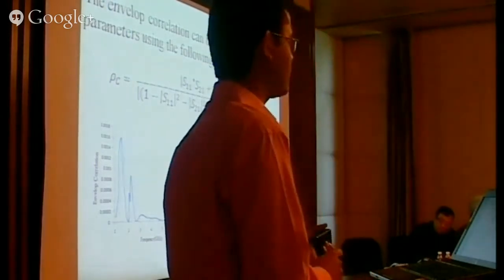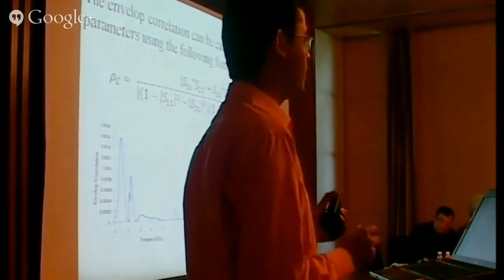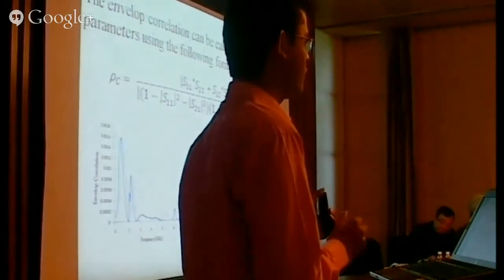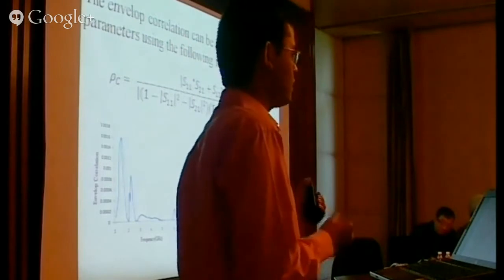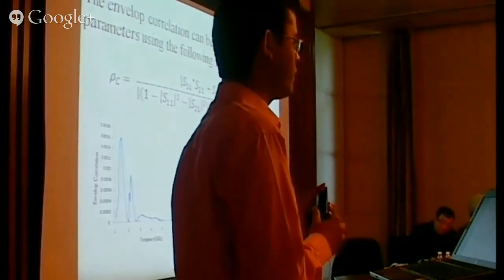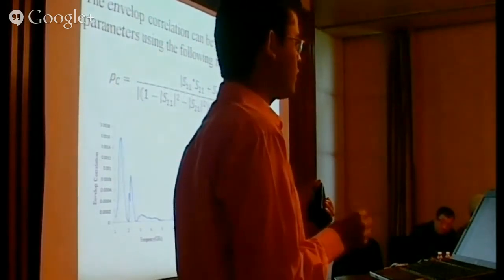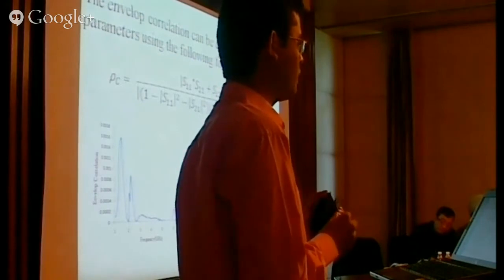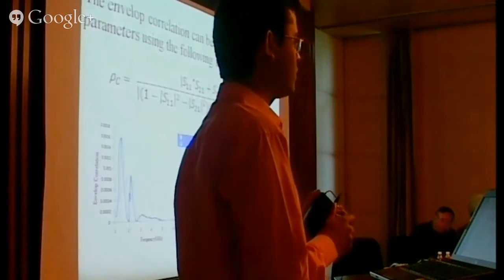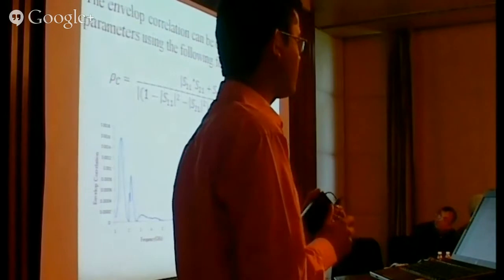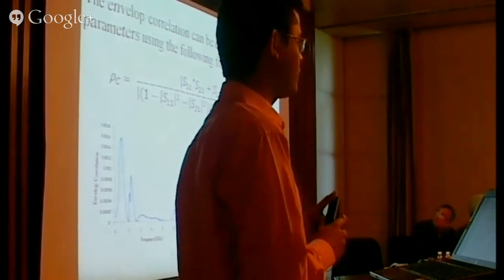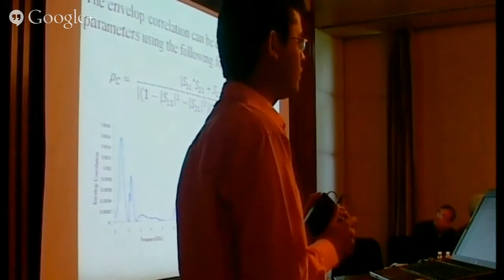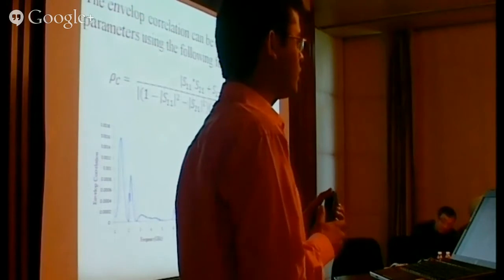Actually, sir, there are some techniques to use a decoupling structure in the ground plane. It is also known as a defected ground plane. Using the decoupling structure in the ground plane, the isolation can be increased. Recently, I found in some papers that isolation can be improved using the decoupling structure in a ground plane.